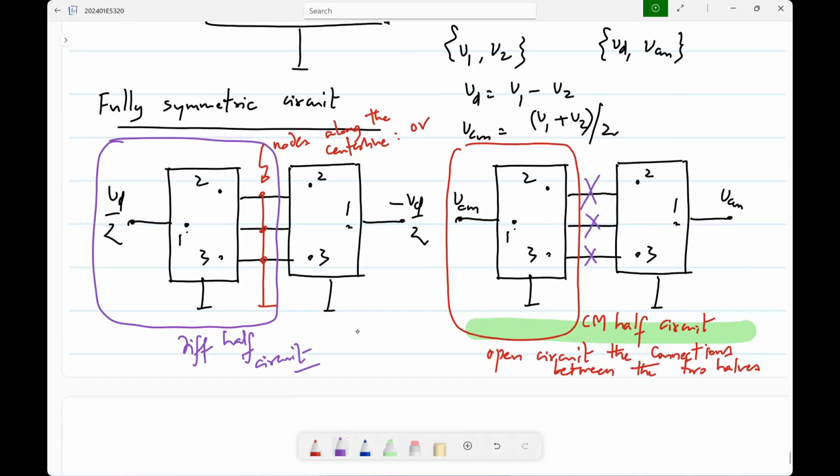Now everything that you know about negative feedback will come in handy there as well, because that's yet another feedback, but only for the common mode. Okay. So all the circuits that we have so far, the single stage op-amps and the 2-stage op-amp and so on, can be converted to fully differential versions. Now the circuit will look more complicated initially, but first of all, you will find that the frequency response is actually better in some ways compared to the single-ended op-amps, which are asymmetrical. So what aspect of the single-ended op-amp frequency response was because of asymmetry? Do you remember? There's one particular thing that was because of asymmetry. What was it? Yeah, that pole zero doublet, right?